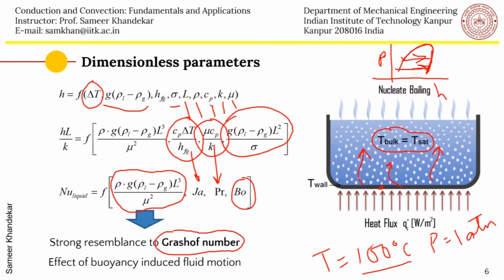So you see the Nusselt number now depends on the Jacob number, the Prandtl number, the Bond number, and this Grashof number looking type of number, which is also called the buoyancy number; the effect of buoyancy induced flow motion is what is captured by this number. So there are four basic non-dimensional numbers on which nucleate pool boiling will depend.